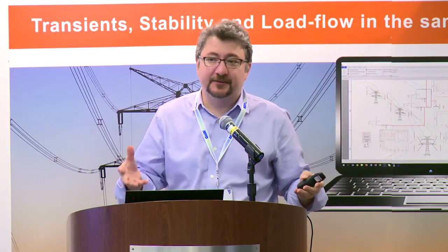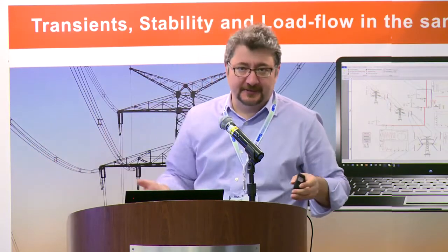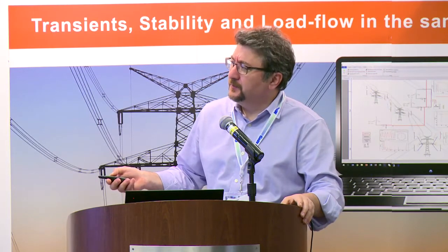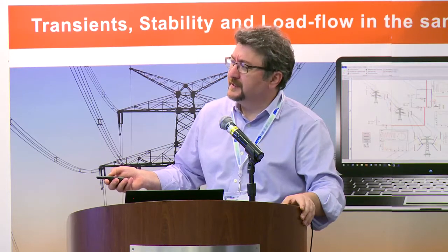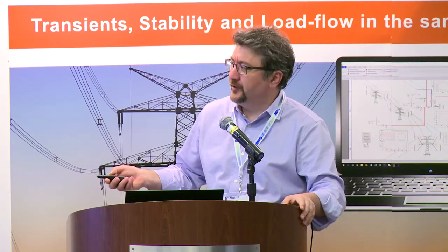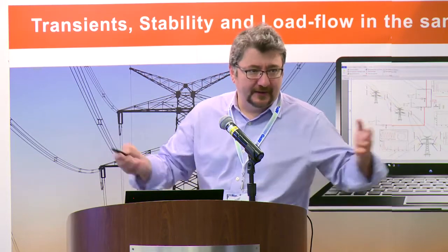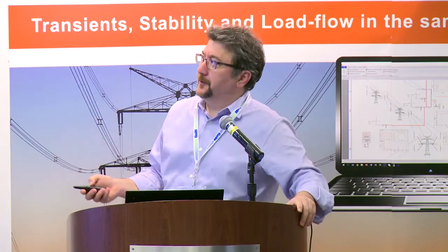The transformation itself is actually frequency dependent. So you decouple the modes for a certain frequency, but this matrix doesn't work for another frequency. But for lines, this is not a big problem. So the FD line model does not consider the frequency dependence of the transformation matrix, but the wideband model does, because it is in phase domain. So we consider the frequency dependence of everything, the propagation function in phase domain. So this is how the wideband model works.